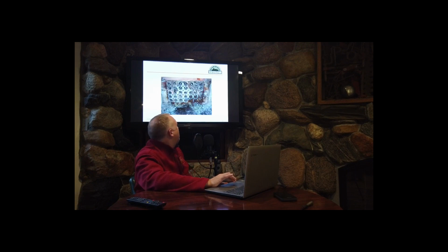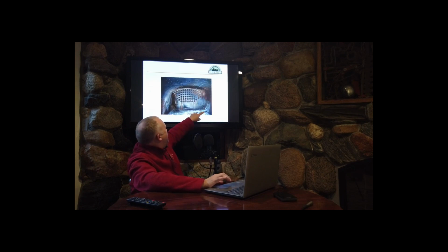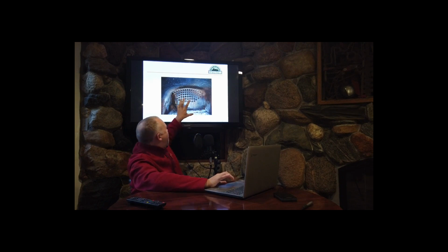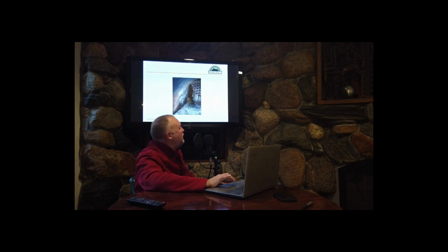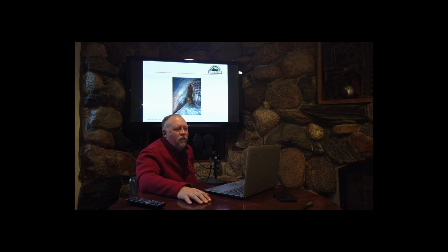There's another picture of the natural gas nozzles. Now, see the bricks? So the fire is right here. The fire goes through these tubes and makes a loop through the boiler, the water section. So this is the fire side of the tubes. Look at a little close up here in the corner. You'll notice one of these tubes was leaking. Notice there's a big pile of rust here. One of these tubes was probably leaking for most of the winter.